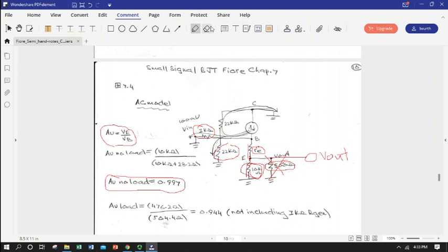But we don't have a full open circuit there. We don't have an infinite impedance at the output. We have a load resistor, and it isn't real big. Remember in our last example it was 33K. This time it's only 500. We're going to get a fair bit of current flowing through that. And in fact, if we apply Ohm's law starting at this point E, we got a 10 kilo ohm resistor here and only 500. More current's going to flow through that load than through our 10K R big E here.